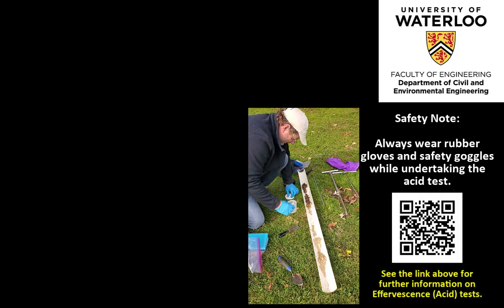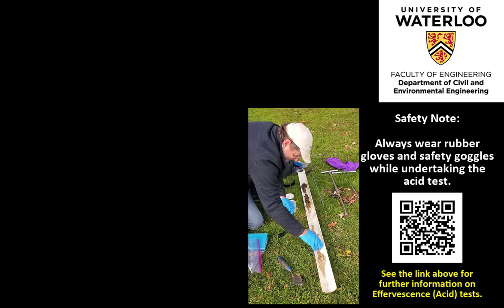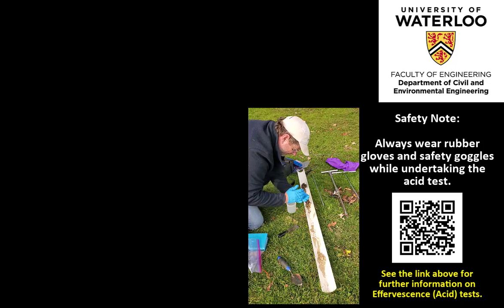The level of effervescence is related to the mineralogy of the soil and parent material. Vigorous and strong levels of effervescence, such as in diatoms or limestone-derived soils respectively, indicate a notably high presence of carbonates, which would also indicate a high pH of the soil horizon.